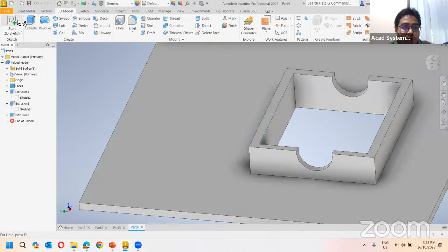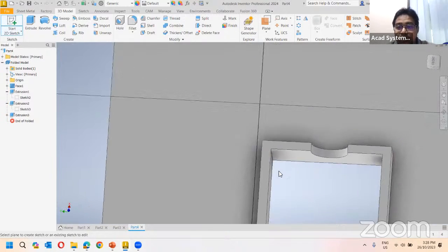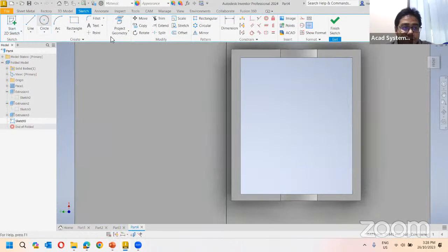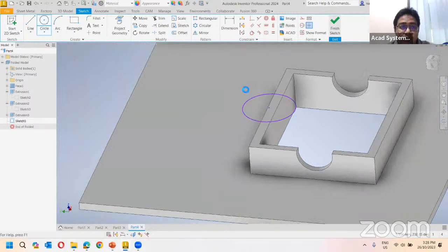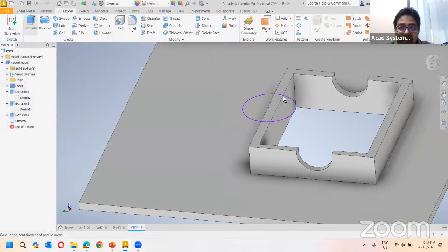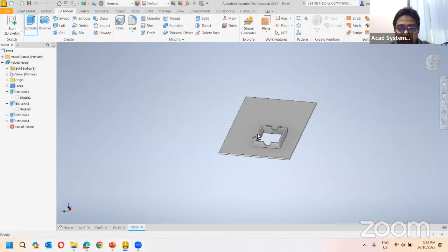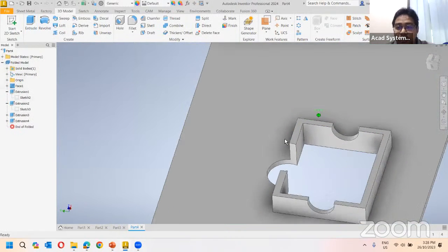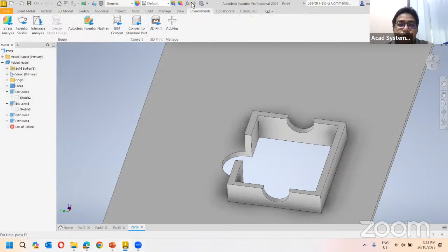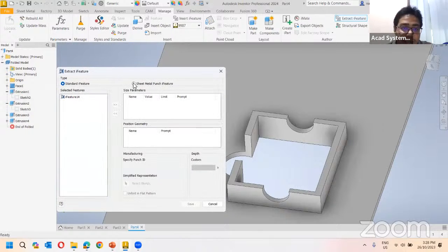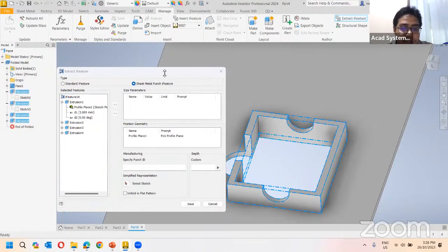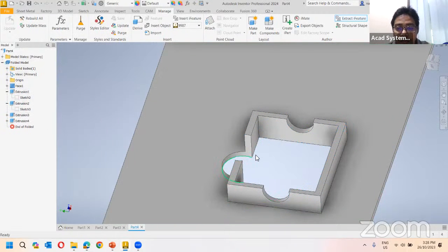Right? So let's say I try again. I put the sketch over here. I click here, and I want to cut this through. Right? So there is no project geometry created. So I just cut, and it also penetrates my sheet metal here. But it still works. So you are still able to extract these punch features. Right, so everything can be selected, and I can hit save.